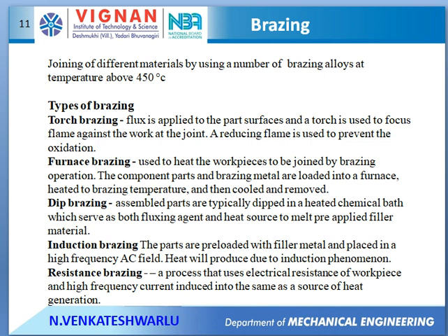In furnace brazing, the furnace heat is used to raise the temperature of the filler material. By using that heat, the filler material is melted and supplied to the narrow zones of the components to be joined. The furnace may be an oil or gas furnace or an electrical furnace.